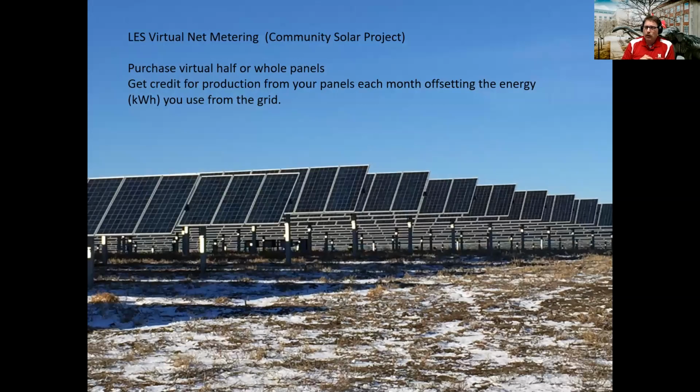LES has a community solar project, and they call their system to buy into it virtual net metering. Remember, I just consulted their website and talked with them to make sure I got this slide accurate, but I think they're going to present a little bit later on some of the details of this. But you can purchase half or whole panels from this system. You get credit for the production of those panels each month, offsetting your kilowatt hours of use. So it's kind of like net metering where the solar was generated somewhere else, your kilowatt hours were used at your home, but they offset equally to that amount. And so it's a virtual net metering setup.